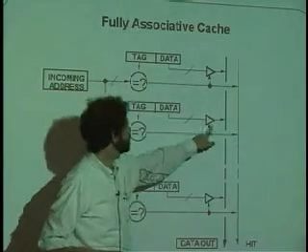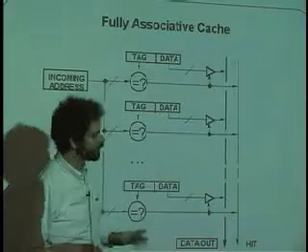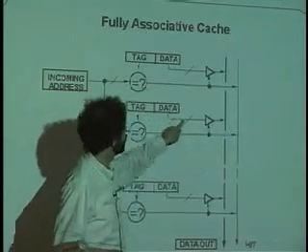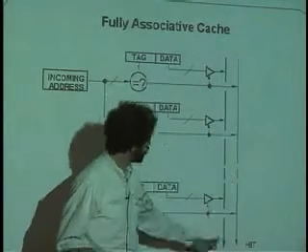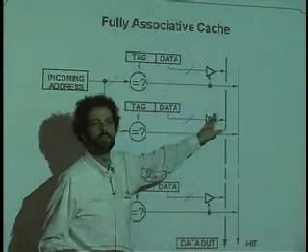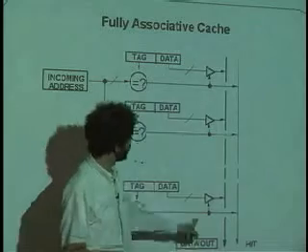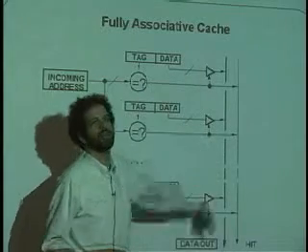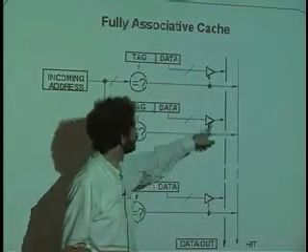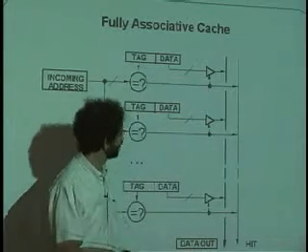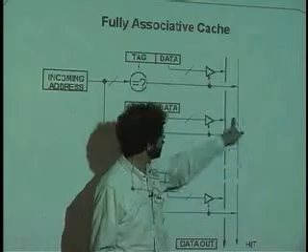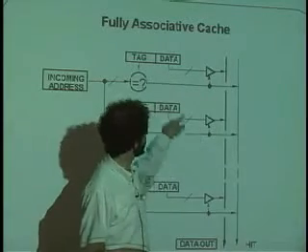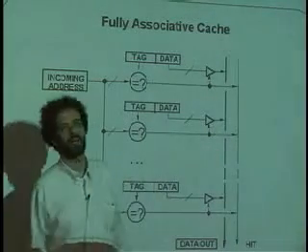And so we enable, this is actually a type of gate that you guys haven't seen here, but it looks like a buffer, but it has a wire that goes into it on the side that says, go ahead and allow the data here to pass out to over here. You can think of it just like a switch. You can think of all of these triangles here as a giant selector for choosing which of the inputs here gets to go out. Except the controls for it are the individual ones on each one of these gates here. And so there's a big OR gate, which I haven't shown here, but if any of the equal signs fire, we get a hit. And whichever one fires steers its data to the output lines, and that's the data out that comes out there.